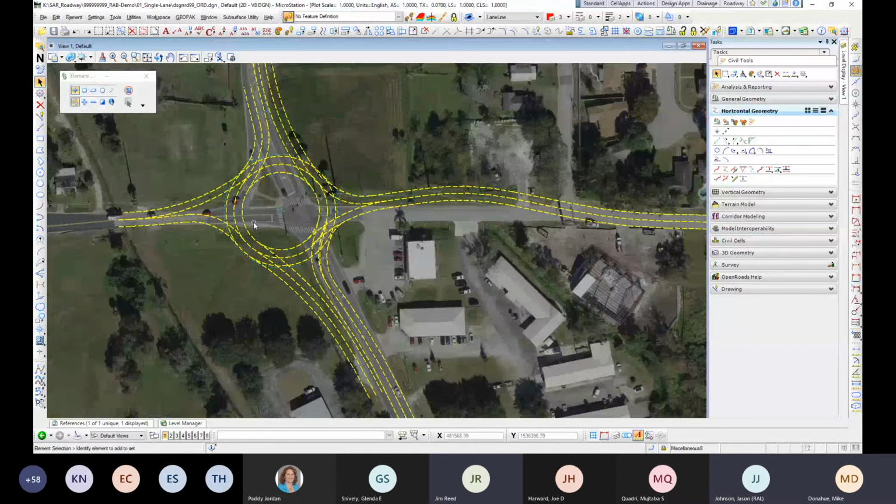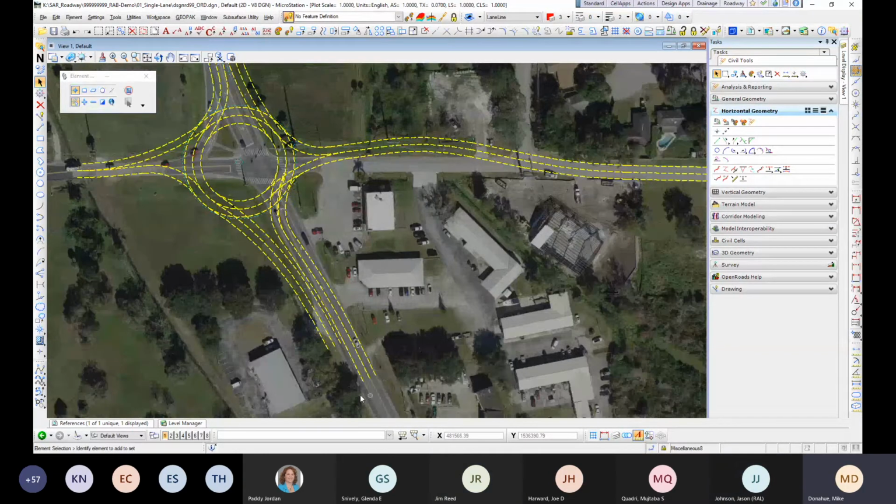I think what you're going to find is it's going to be a combination of all of the above. For the approaches, where you have what looks more like a typical section represented in your plan, with pretty symmetrical lane assignments, your median may vary, you're going to run a template to address most of that, with flexibility in the cross slope built into your template, whether it's a parametric constraint, or you're using superelevation shapes or outside edge of pavement profile, what have you.